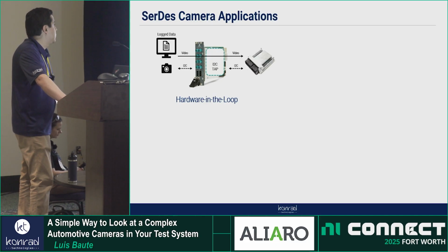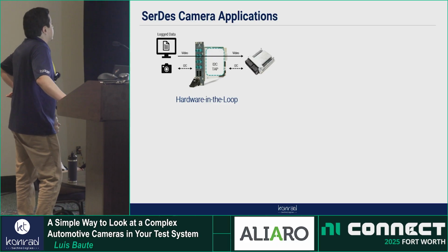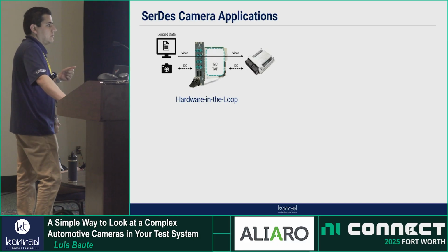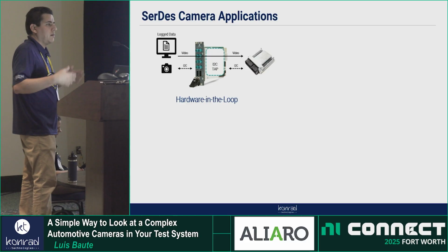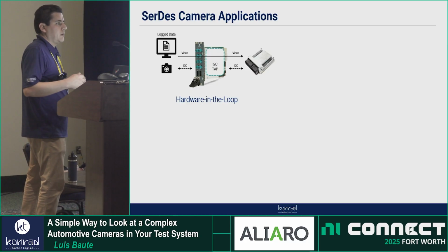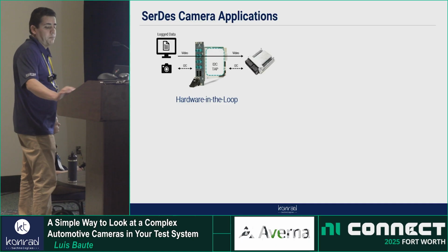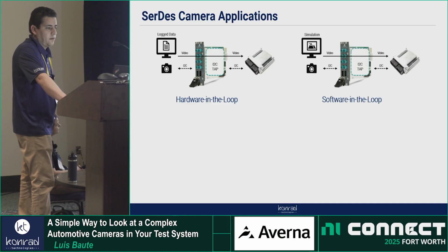There are hardware-in-the-loop projects that could be done with this one. For example, let's think you have your PXI and you mount it in the car, you put the cameras and you start recording all the data. And then you can just replay that in a lab or your test bench.